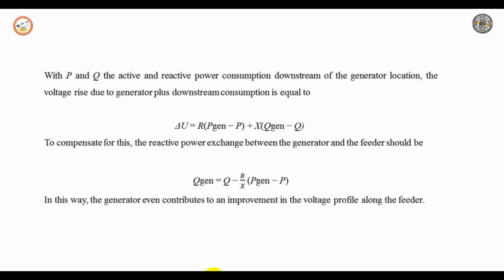With multiple units, each unit can compensate its own contribution to the voltage magnitude variation, and in that way limit the total voltage variation, where the risk of overvoltage will no longer be a limitation for the amount of distributed generation that can be connected.